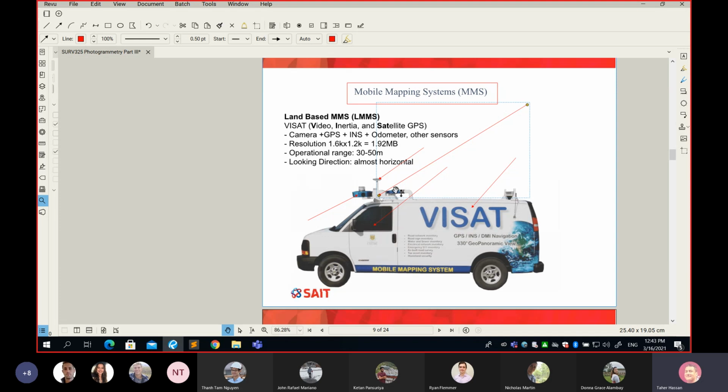They are good for the purpose of the phone, but this INS here still has the same accelerometers and gyroscope, but those are very expensive because they are very sensitive. They can sense very little motion of the platform, so we can get a millimeter level of accuracy, okay? I can give you a number for this one. This guy here is about 100,000 US dollars. The price of the INS is 100,000 US dollars.